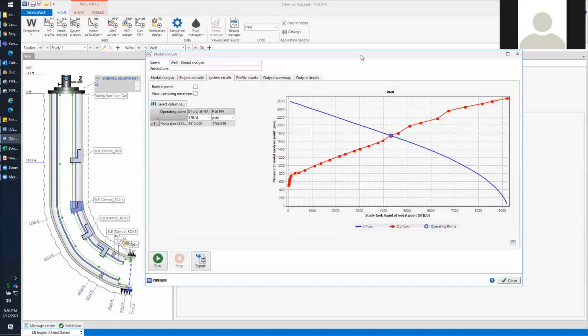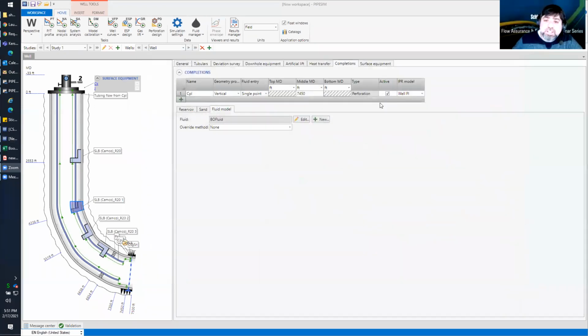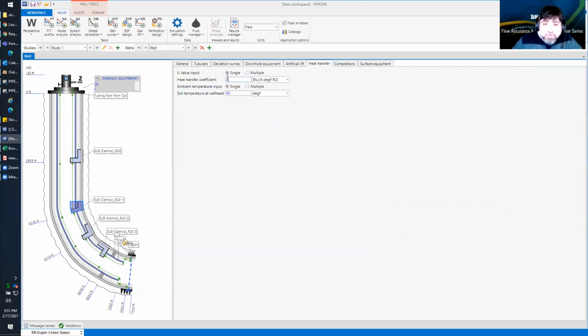I see. Thank you. Another point is that you defined the heat transfer coefficient as a constant. Does the OLGA-S model count it as a constant coefficient as well, since OLGA-S is a mechanistic model which solves the energy, mass and momentum equations? Yes, it will consider this value as a constant, but remember, it will calculate how much BTU is transferred based on the temperature difference and the area.